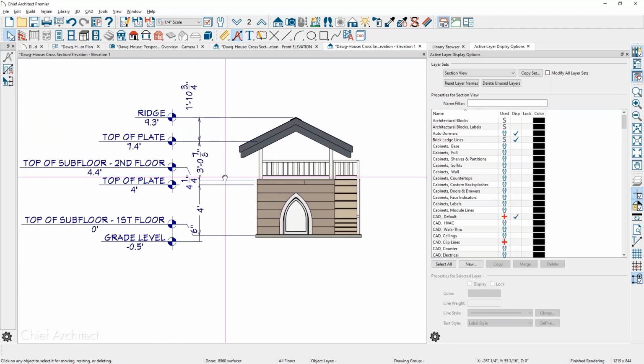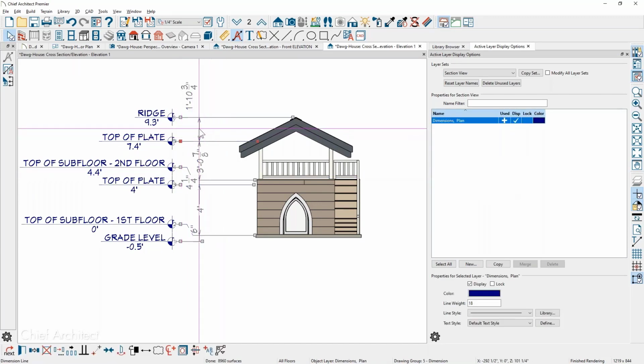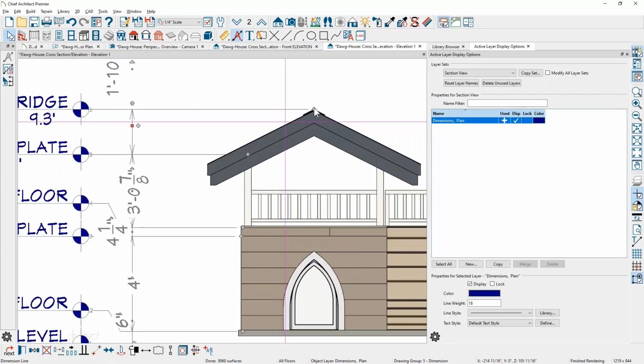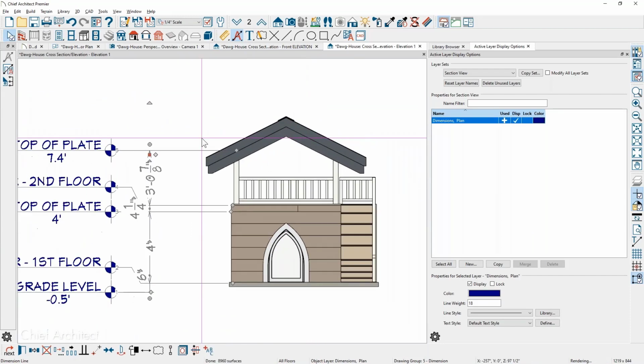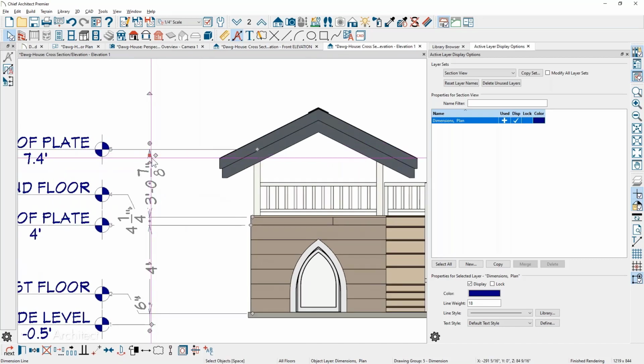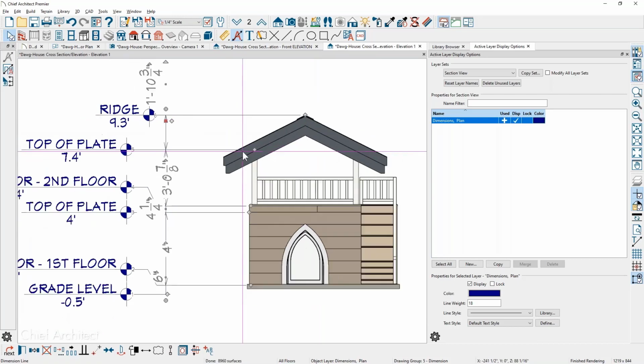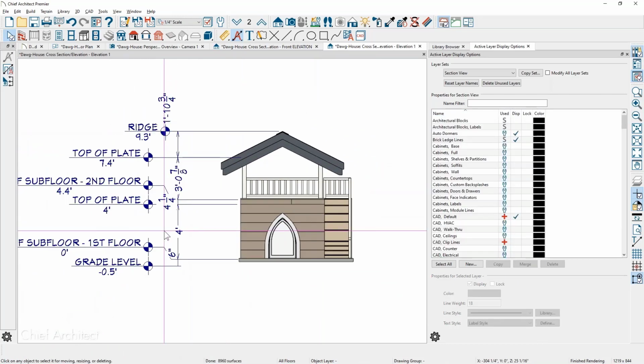And then it's pretty easy to customize this. You can click on the dimension, and when you see a diamond, you can just simply pull that off a little ways, remove it off the ridge. And then if you want to add a dimension, let's say maybe you wanted to click on that and put it back on the roof. There's an extra diamond wherever you click typically. So you could pull that back in and position it to create that.